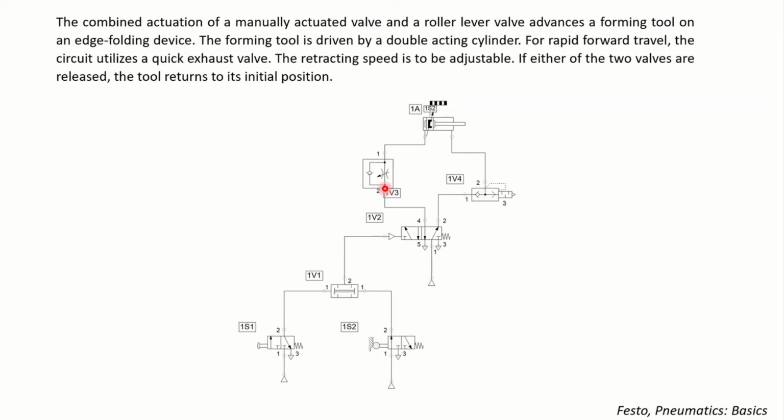We already discussed how the throttle check valve works. First, it looks at this side, and it is basically a free path. The air notices it has a free path, so it decides to move this way, and then it gets inside this double acting cylinder. The pressure results in the force needed for moving this piston towards the fully advanced position.